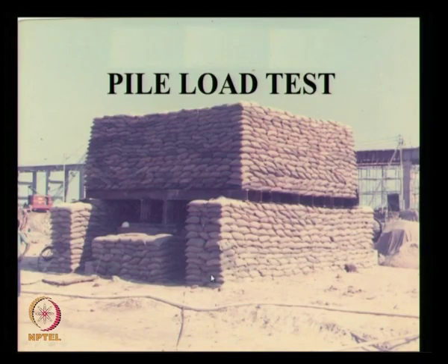This pile load test is mandatory. Mandatory means it is compulsory to carry out the pile load test. Some percentage is given. There are two types of tests. One is the initial pile load test and another is the working pile load test.